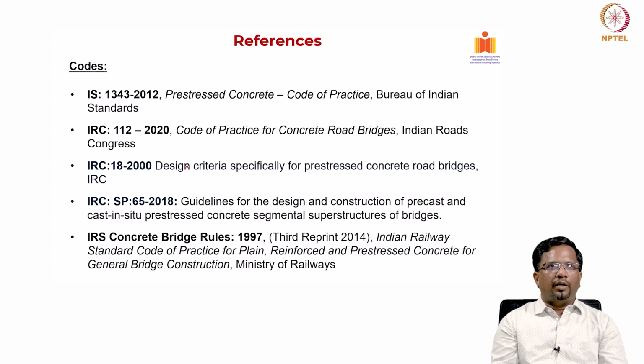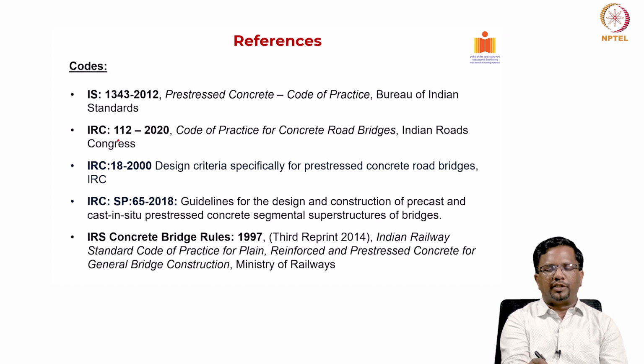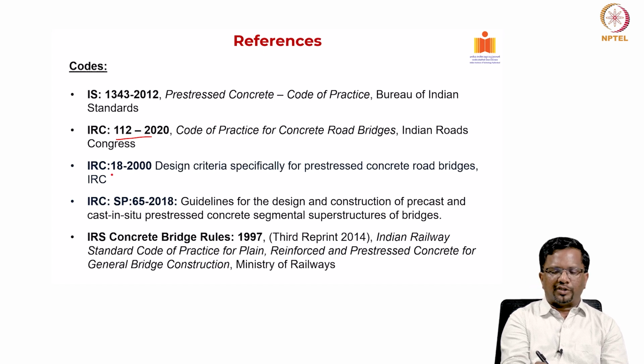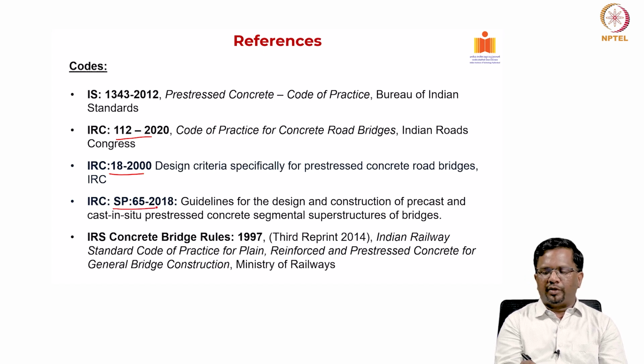Again, with respect to road bridges, we will be following Indian Roads Congress publications, which is IRC 112-2020, and for prestressed concrete load design criteria we will be following IRC 18. And there is also a special publication from IRC, which is SP65, for design and construction of precast and cast in situ segmental construction. So, we will also use some of the provisions of that.